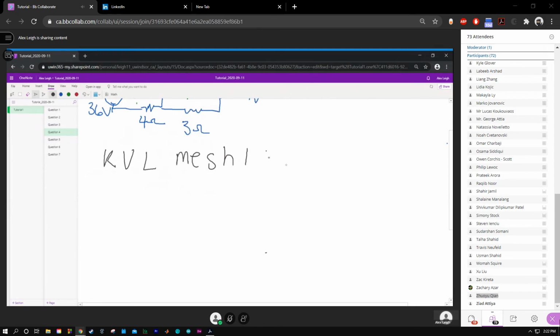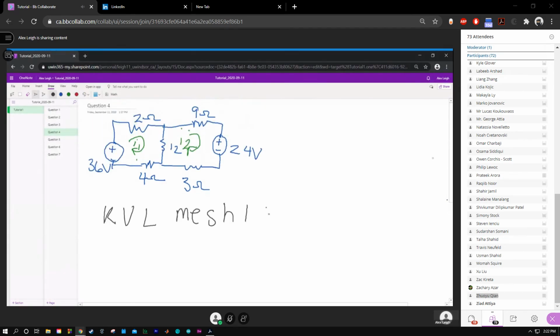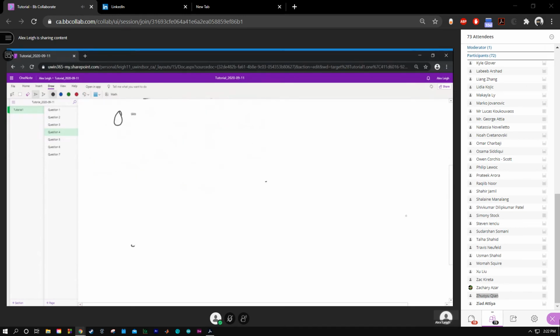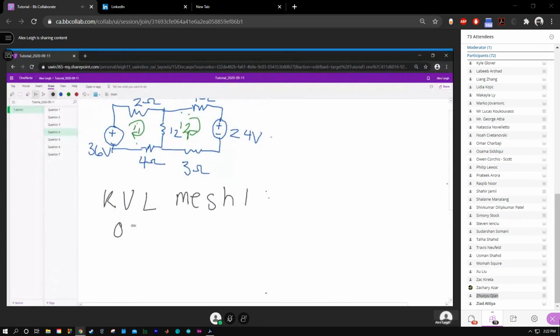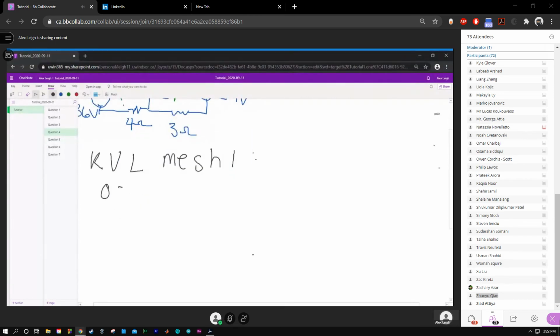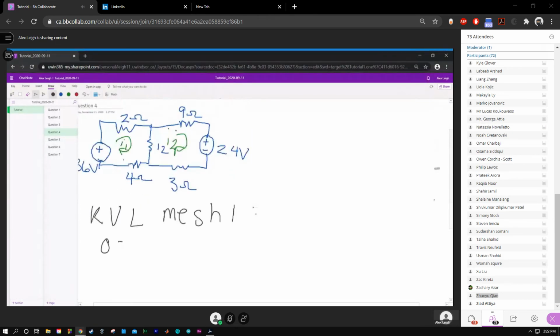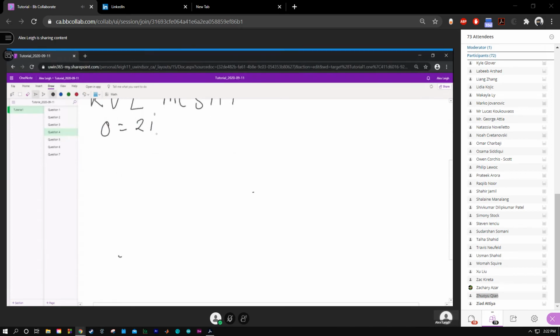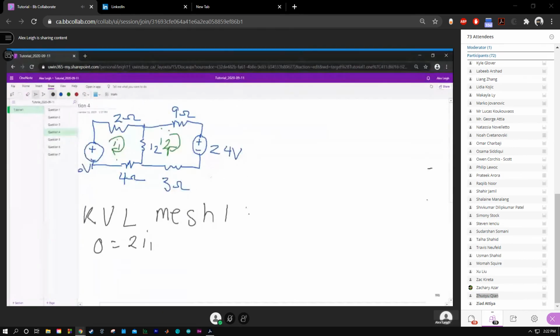Okay, so first thing we have is its voltages. This is not currents anymore that we're measuring. So we've got 0, because the sum is 0. And we use Ohm's law to determine the voltage, just like we use Ohm's law to determine the currents. So Ohm's law means current times resistance will give us voltage. So this one here is 2 times I1.